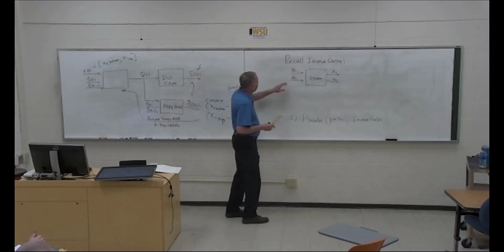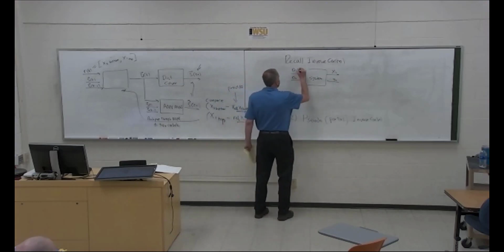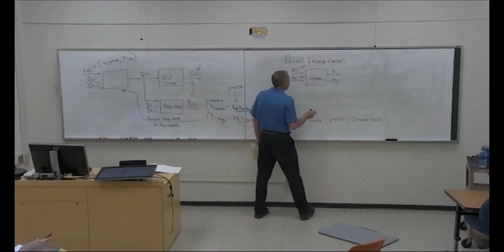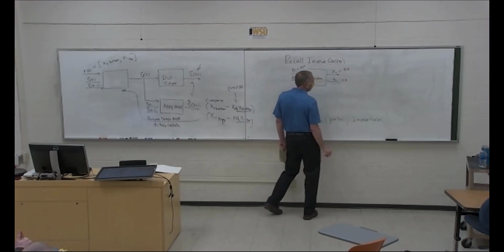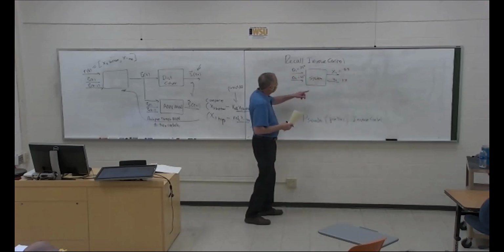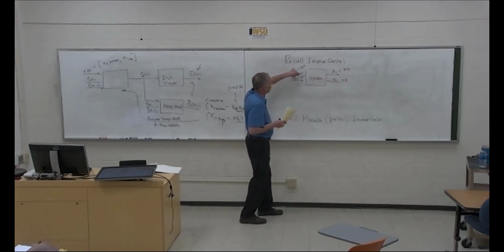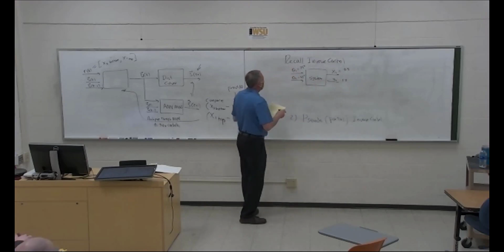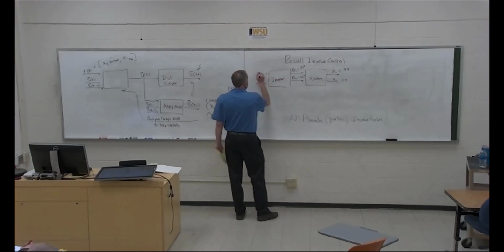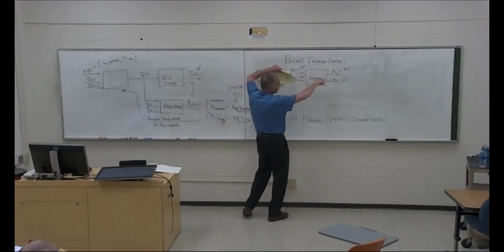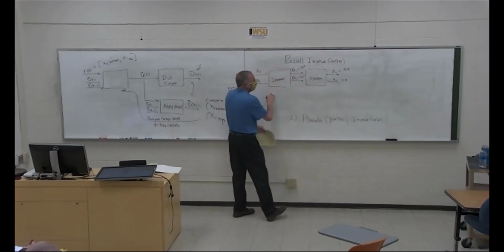So if we put in a theta of 25 degrees and 45 degrees, and we get out a position of 3.5 and 1.2, if we want to put the arm at 3.5, 1.2, this is what we want to use. And so that becomes the training for the inverse control. So you run the system, collect a whole bunch of data, flip it around, and train the inverse.